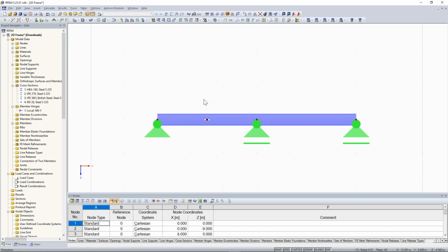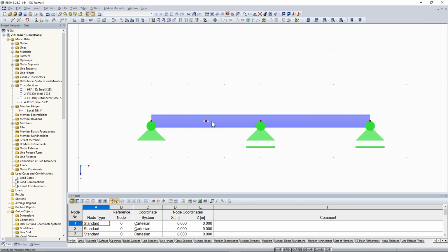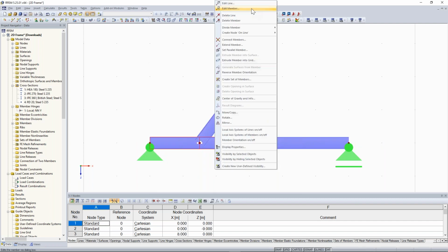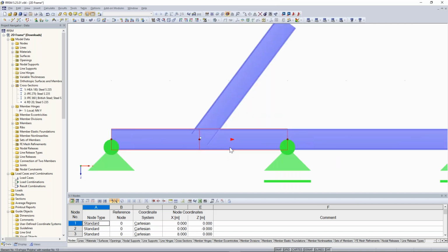And also when you have here maybe any diagonal connection, for example a truss or something like that, and you want to connect this here also with the help of a hinge, then it's very easy. And this one you can delete. Sorry, my fault. Then you have here this member hinge connection. Yeah, this is correct. And when you would have here 3 additional member hinges, then it would be false. So much to the hinges.